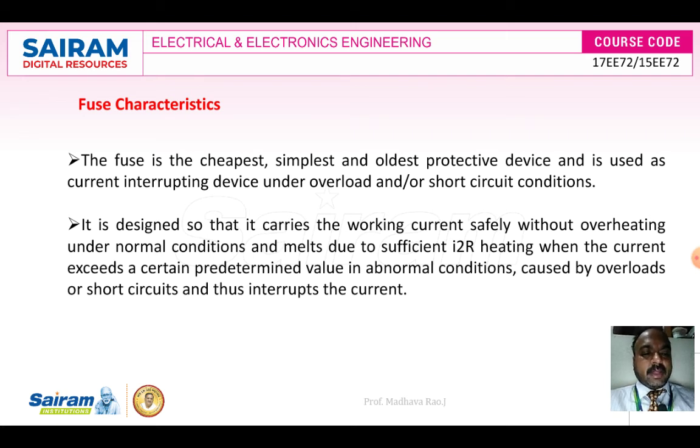Whenever abnormal conditions occur, that means the fuse carries more than the predetermined value, the fuse element will overheat, get damaged and break the supply. So that is about the fuse characteristics.